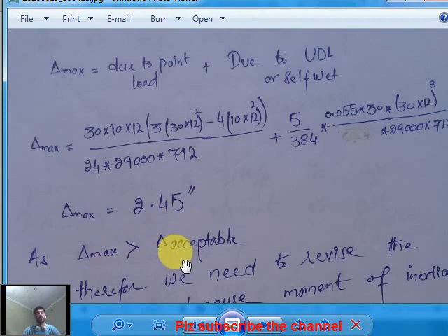Always select the section on the basis of the IX table. If you have to check your deflection limit, remember, I already explained this point in those lectures. Because if you select the section under ZX, although it will pass your first check, that is for moment, but sometimes it will fail in deflection.